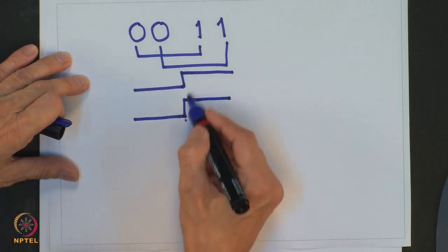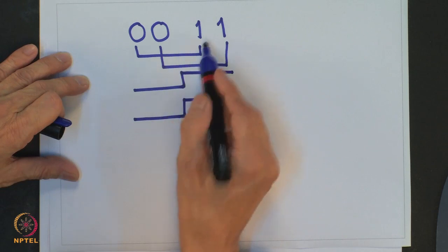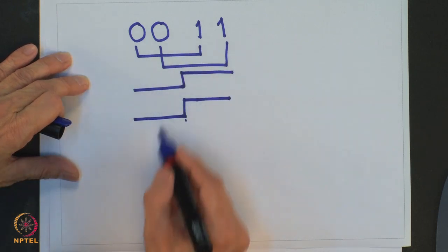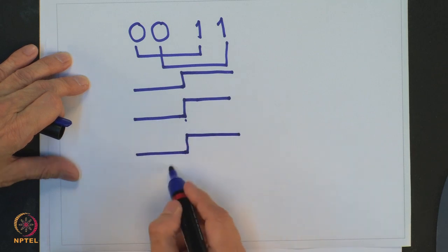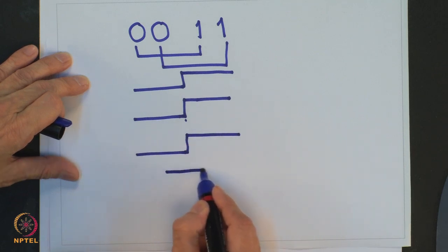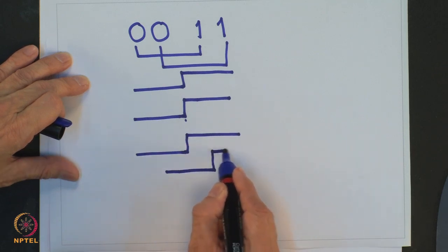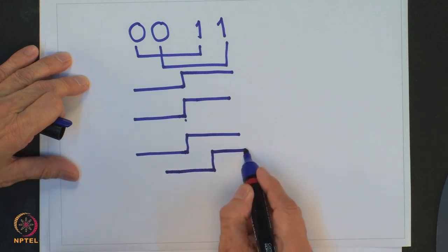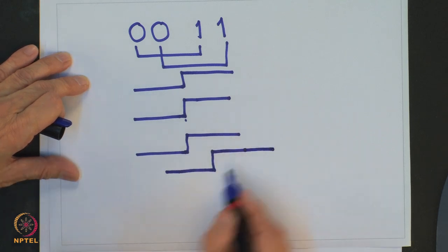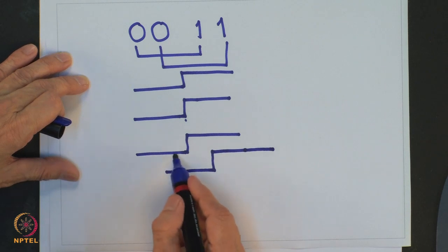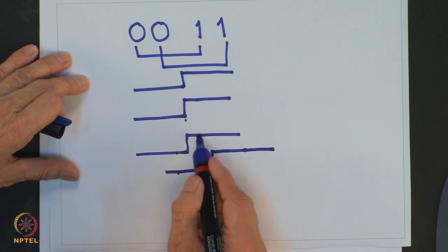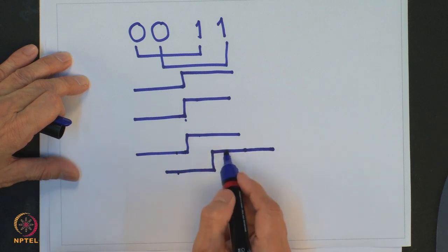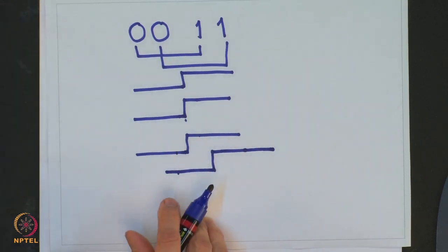So, at this instant both of them change, but now with offset QPSK what will happen? This will remain as it is, and this will shift by 1 unit, not to scale again please. So, you see basically during the Tb duration this is 0 0, then it goes to 1 0, and then it goes to 1 1, correct.